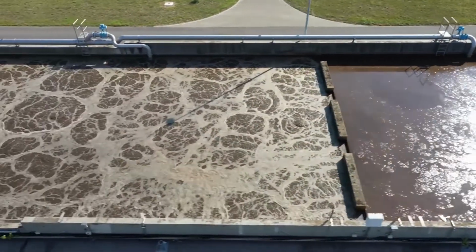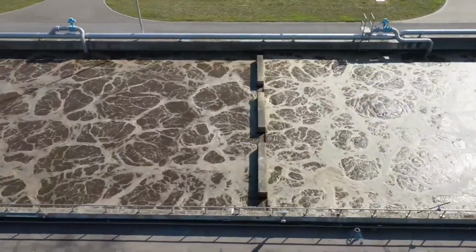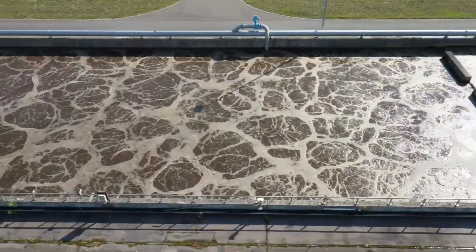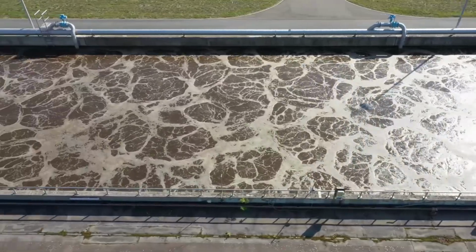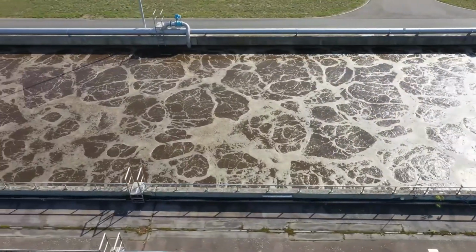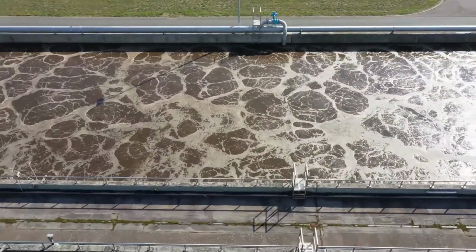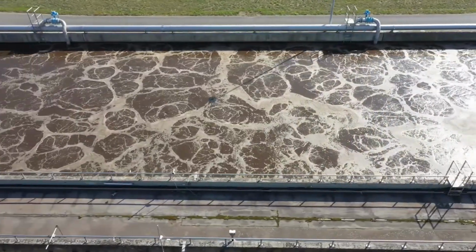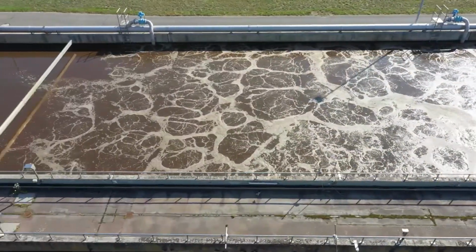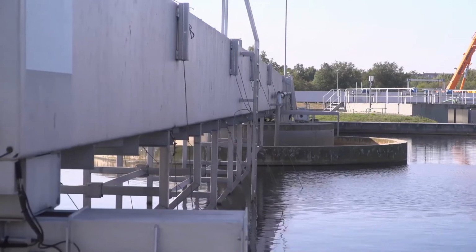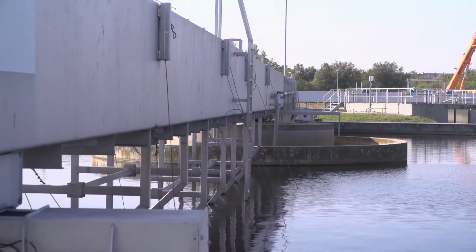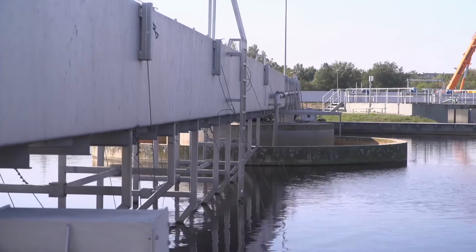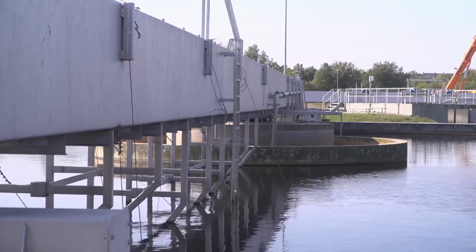Finally, the resulting mixture of activated sludge and wastewater is subjected to another denitrification process. Depending on the system design, recirculation pumps transport some of the bacteria back to the start of the process so they can perform further work. Some residual bacteria ends up in the sludge treatment process. The treated water flows back into the final clarification tank.